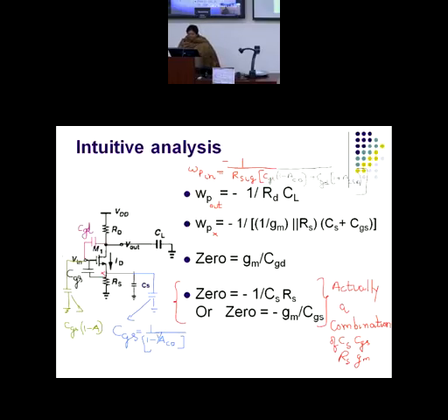So you have to now add all the time constants together. Now what is the net resistance at node X? It would be Rs in parallel to 1 upon Gm. There is an up component, there is a down component. The down component is Rs. The up component will be looking from the source up, that would be 1 by Gm. So that is why 1 by Gm parallel Rs, which is this. Look very carefully. 1 by Gm parallel Rs multiplied by the total capacitive load.